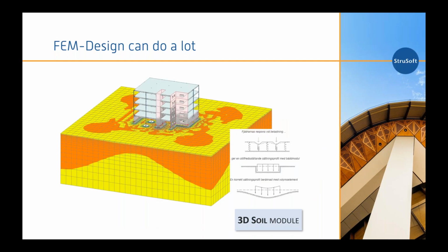You can also study the soil as a 3D finite element. This is a very accurate way of studying the soil together with the superstructure in comparison with a spring model or a bedding modulus model. The 3D soil gives the most realistic behavior of the soil.